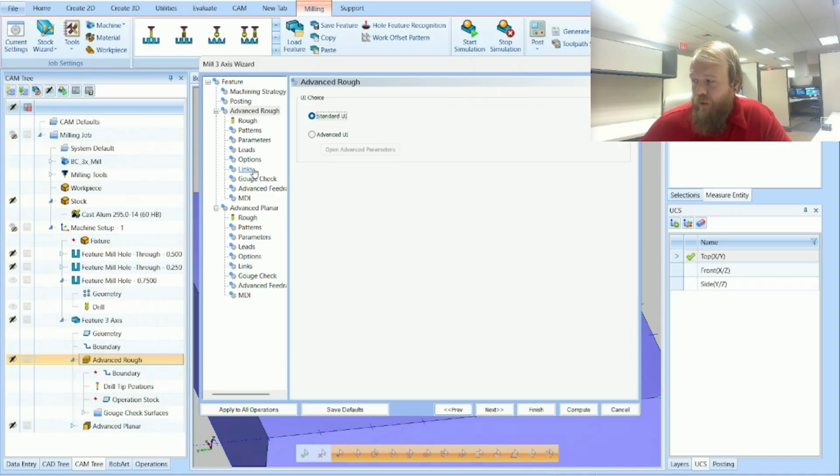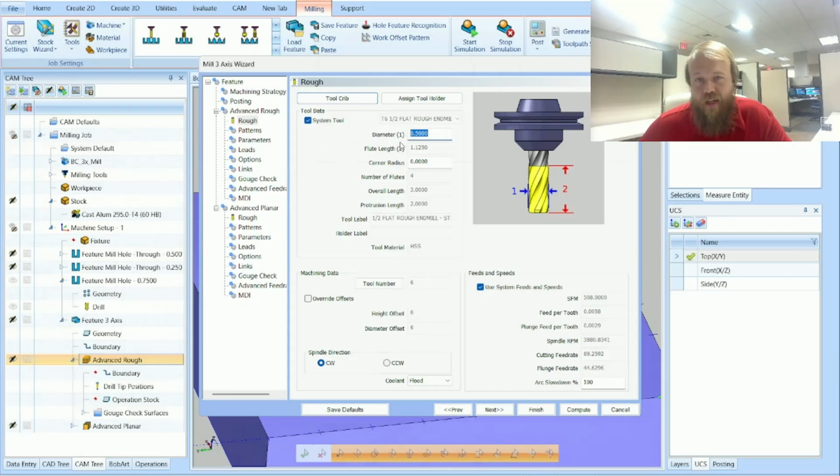So rest machining would be more when you do a tool change, like to a ball mill. Yes. So it would be like if you've got a 1/2-inch flat end mill, then you're using a 1/4-inch ball end mill, and then maybe going down to finally your last tool that you're using, this sort of semi-finish operation you can use with rest machining and just machine from what you've left off with down to what you can with this tool, and then finish up with the last finish operation there.